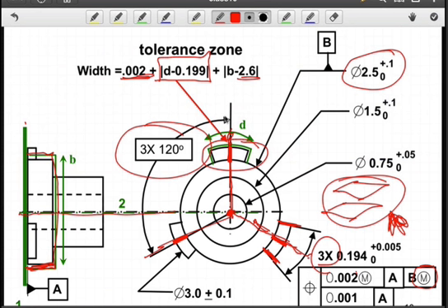The feature locating tolerance zone, we drop the restriction, datum B, because we're no longer interested in the location of the pattern. The shape of the tolerance zone is the same, 2 parallel planes. We don't have material condition in this case, so we are going to fix 3 sets of planes so that they're separated by 120 degrees. That is the only restriction in terms of relative location. And secondly, we're going to orient them so that they are perpendicular to datum A. Again, the size, the width of the tolerance zone is smaller, and so it's a tighter restriction of these tabs relative to each other.